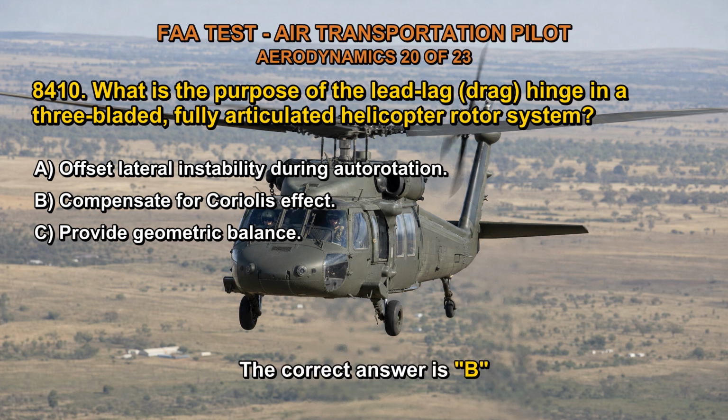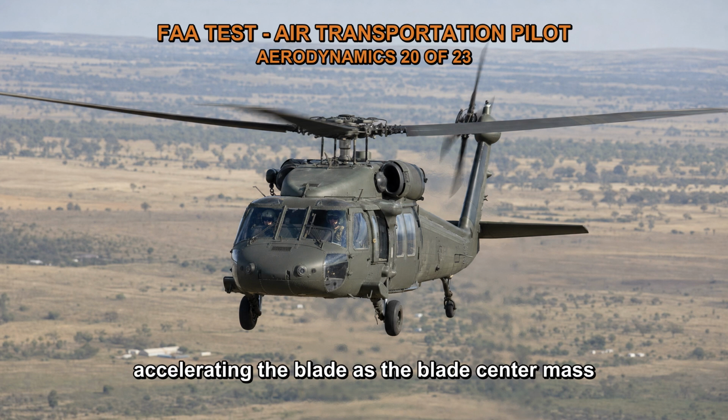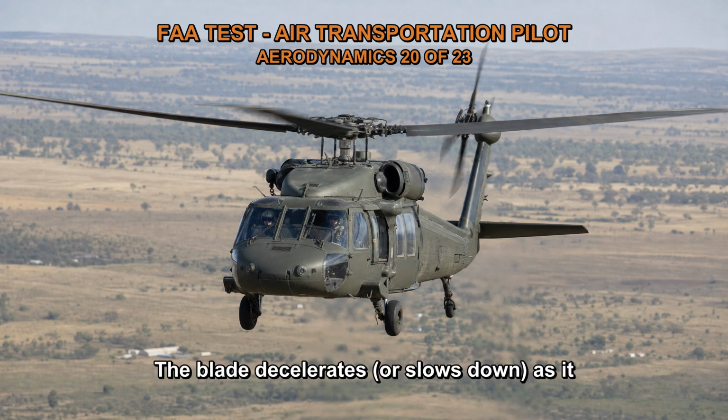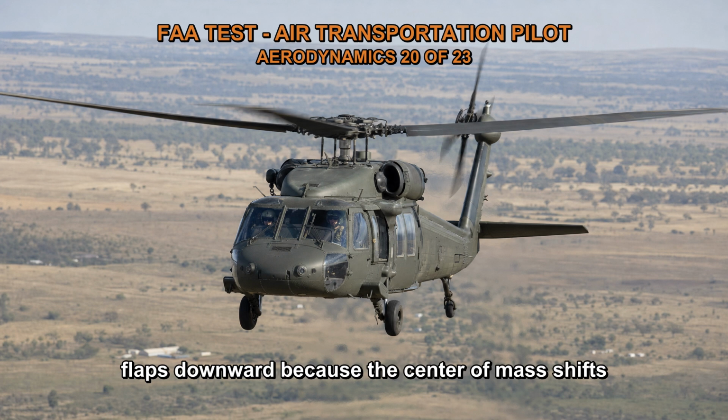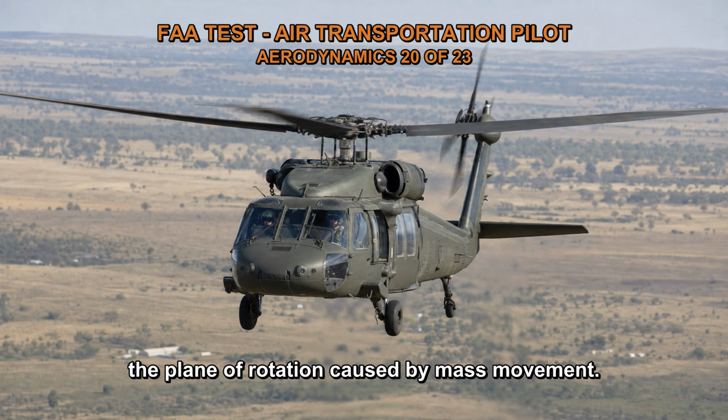The correct answer is B. A three-bladed rotor system's rotor blades flap forward, accelerating the blade as the blade's center of mass approaches the axis of rotation. The blade decelerates, or slows down, as it flaps downward because the center of mass shifts away from the axis of revolution. The Coriolis effect is the name given to the rise and fall in blade velocity in the plane of rotation caused by mass movement.